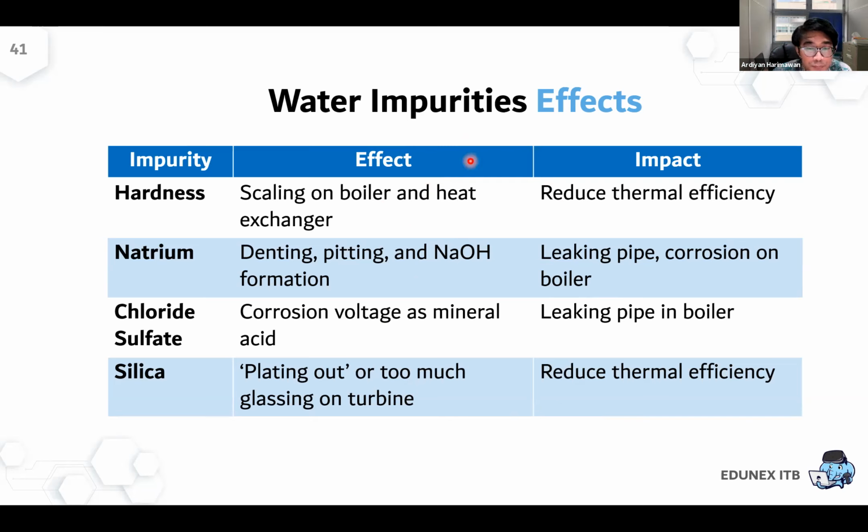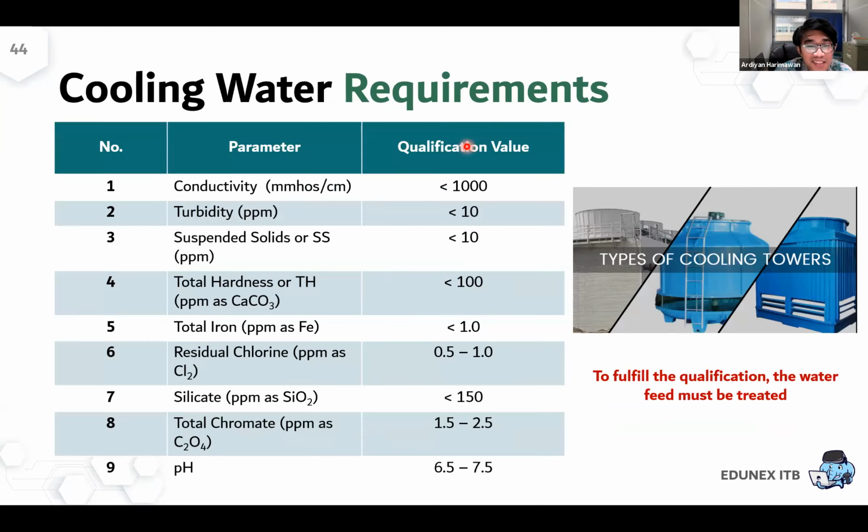Because the investment and the operational cost to treat the water is quite high also. But the repair will be higher. If you have damage in the boiler, for example, your boiler tube is bursting or the heat exchanger is scaling, then the cost to open the heat exchanger and change or clean the tubes, in the long term, is much higher than the cost of water treatment. Okay, any question?